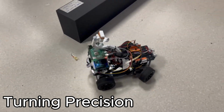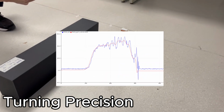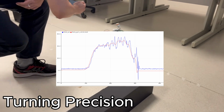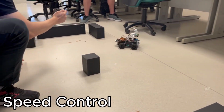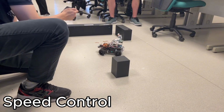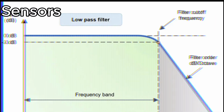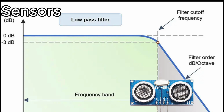We also utilized the gyro's reading to control the servo motor for the front wheels, adjusting the servo to compensate for any unwanted drifts. For the motor, we calibrated both motors to individually adjust to maintain equal speed when moving in a straight line, and dynamically adjusting motor power during turns based on speed differential between the inner and the outer wheels. Lastly, for sensor accuracy, we applied a low-pass filter to the readings for both ultrasonic and IR sensors.